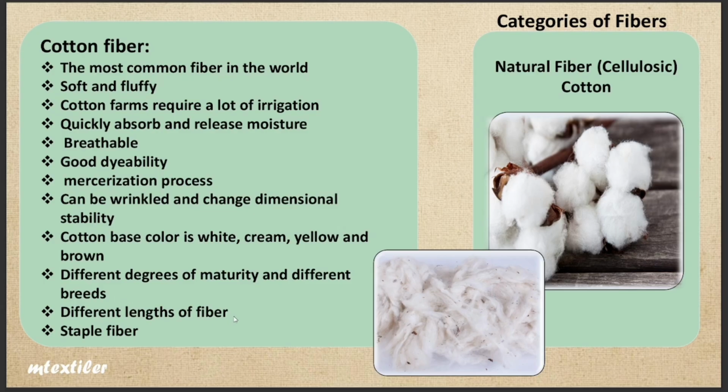Different lengths of fiber. Fiber length is a very important parameter in spinning, as shorter fibers cannot be properly integrated into the yarn structure and may protrude, creating fuzz on the surface. Fibers longer than the optimal length can damage the spinning system. The optimal length for cotton fibers is on average about 20 to 25 millimeters, and fibers up to 32 millimeters are considered long cotton